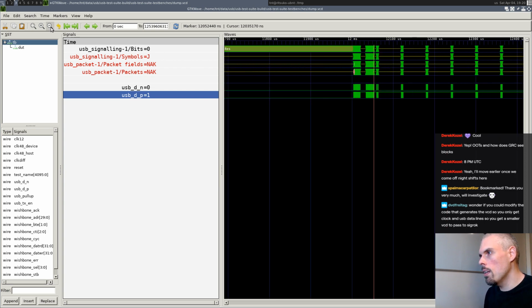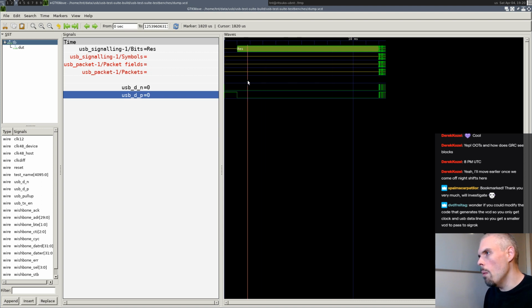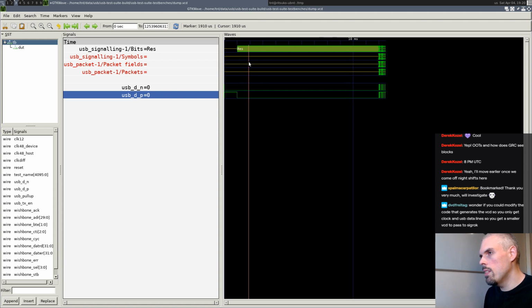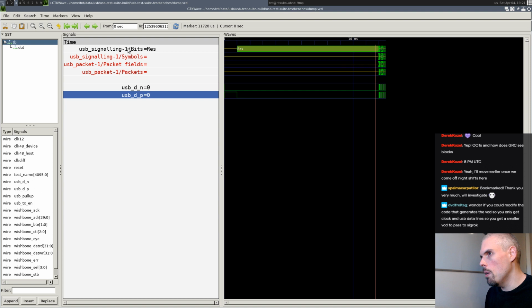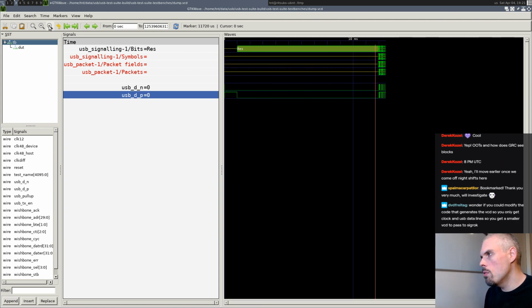I think Sigrok is taking a long time because the VCD that I'm sending has update events basically for every time tick of Verilog, if you will, which means that it doesn't have updates only when the signal changes, but it has one every 1 nanosecond or something. And I think that's why it's taking a lot of time. There might be a way to change the time scale.